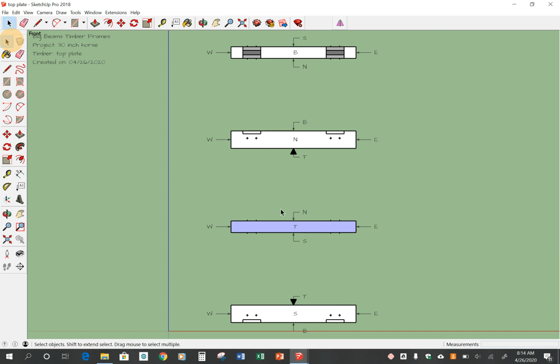So if you look at the overall thing, you will see that this shows the blue painted face, but you'll also see these curious little arrowheads. And those arrowheads would not be there if we hadn't painted our reference face. But by painting the reference face, it automatically puts an arrow that points to the edge that you would pull your measurements from. And this is going to become really important.